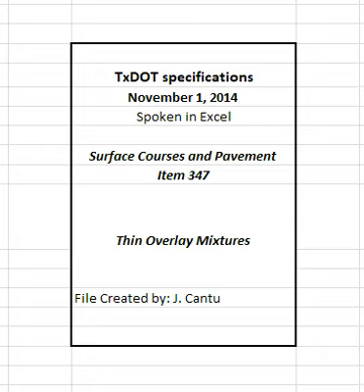The engineer will designate the plant or the quarry as the sampling location. Provide samples from materials produced for the project. The engineer will establish the surface aggregate classification, SAC, and perform Los Angeles abrasion, magnesium sulfate soundness, and microdevol tests. Perform all other aggregate quality tests listed in Table 1.